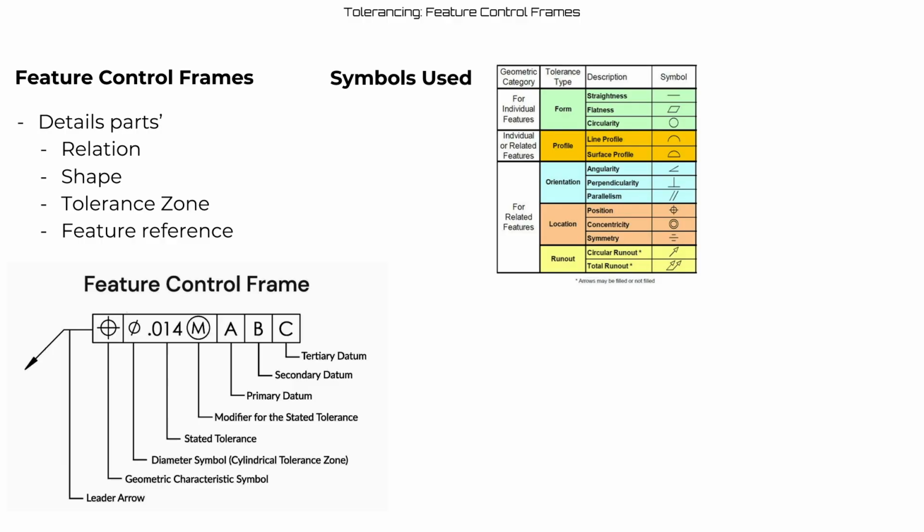Flatness and straightness. I just want to add, because I noticed it's not on the chart, that under circularity there should also be cylindricity, which is basically circularity but for a cylinder. The symbol for that is a circle with 2 slashes on either end of it.